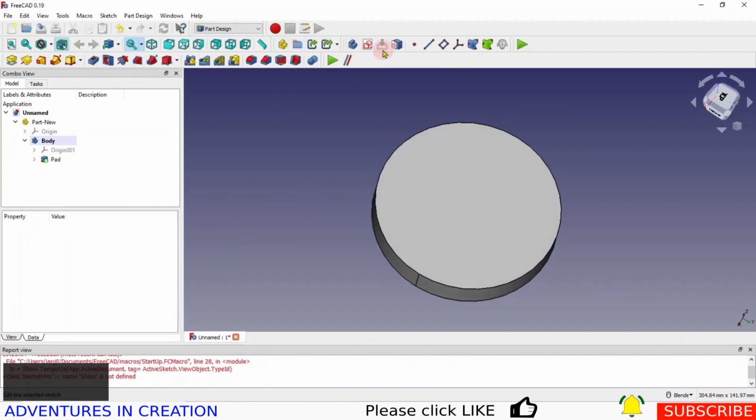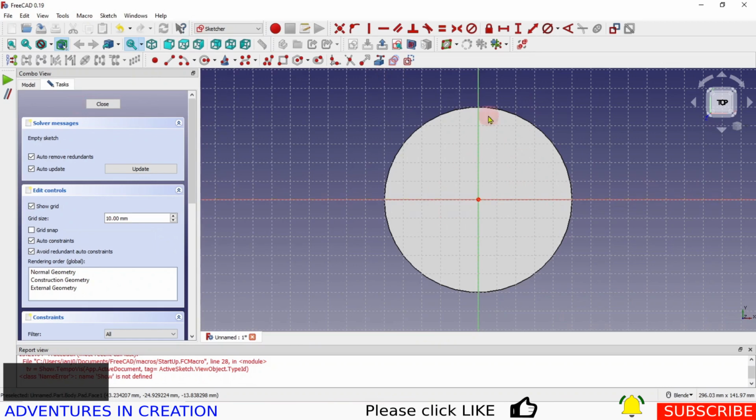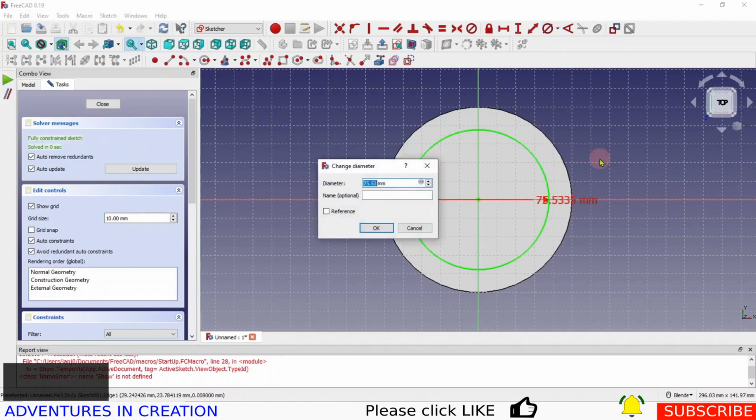So when I do the next sketch, I'm going to use the XY plane again. I can already see the top of it. I can just pop it straight on that center point again. Come out, and this one's going to be 80 in diameter. So once again, I'm going to do it as a diameter constraint and make that 80.